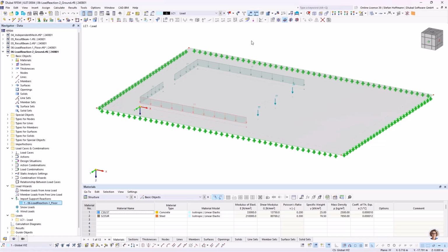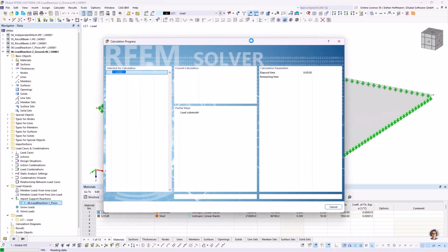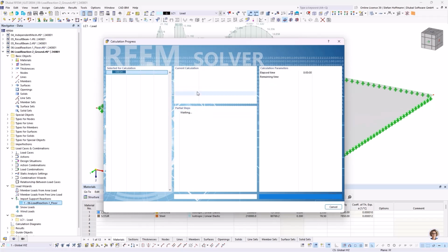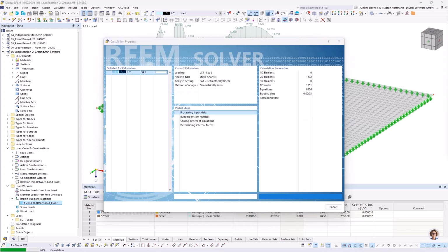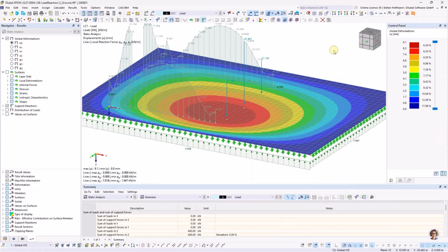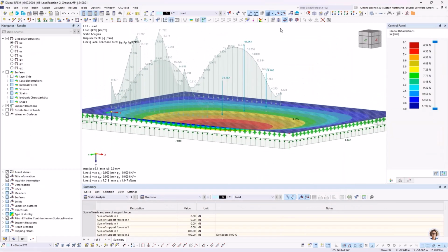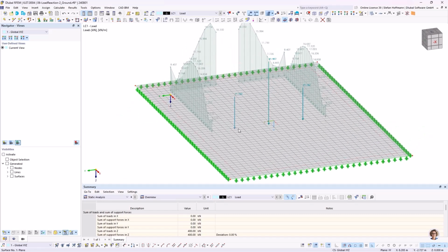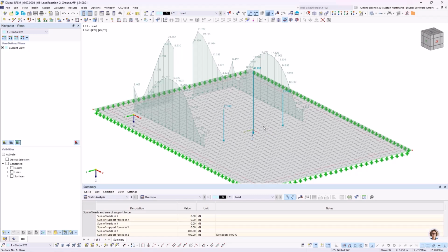The question marks will begin if you hit F5, for example, to start the calculation. It will start the calculation of the so-called mother file, the floor. Once we achieve these results, it will transfer them into our file and then also do the static calculation in our file in order to receive the results. Once we have the results, you can quickly see, if we just display them, that we now have the forces being put into our floor model. Where the door is, there's nothing, and only our column forces are being introduced.